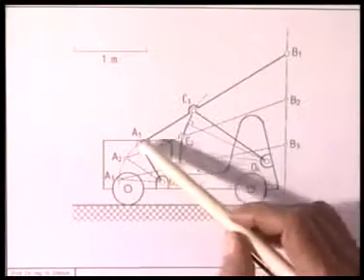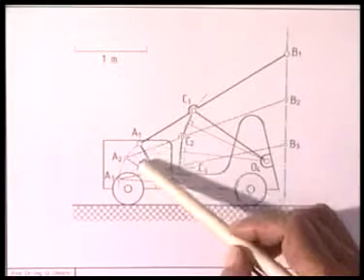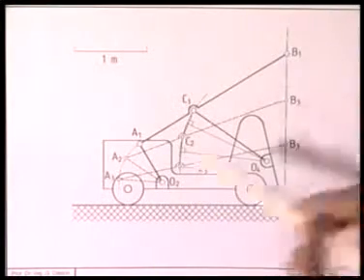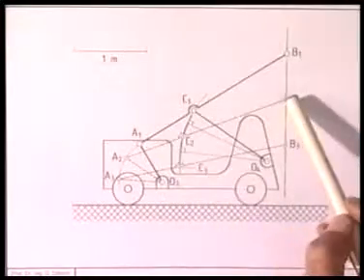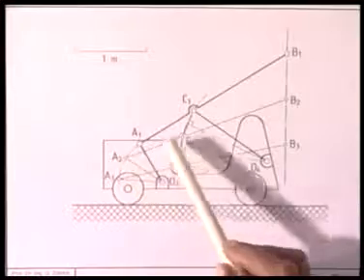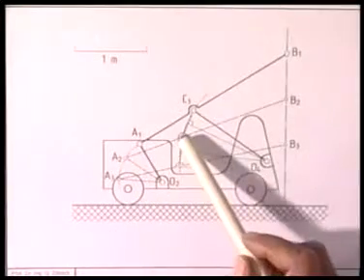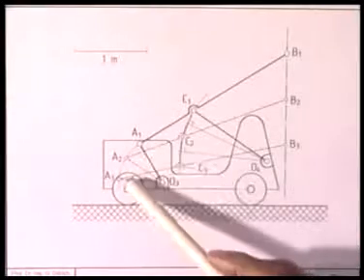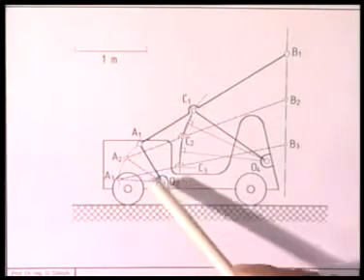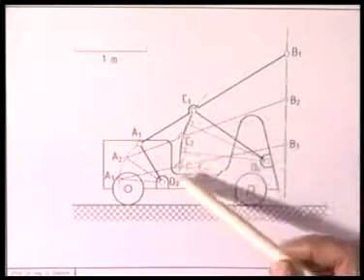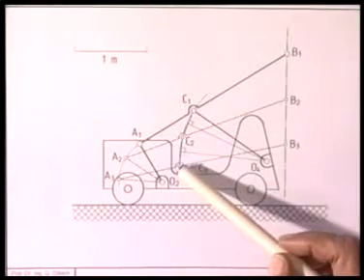I draw A1 goes to A2, that is 26 degree, B1 to B2, that is 0.6495 meter, and I get O2 A2 B2. Because this length is already fixed, so from A2 I measure this length and get to C2. So I locate the point C2. Similarly, in the third configuration O2 A3 B3, I find the corresponding location of C and I call it C3.